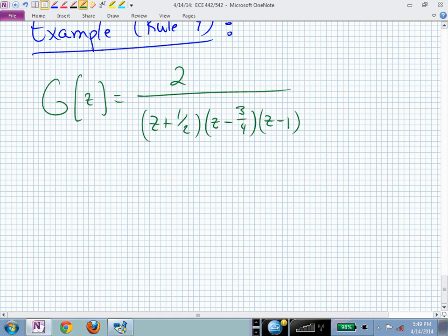How many finite zeros do you have? 0. You do not have any, and you have 3 poles. That says then that our pole zero excess, which I said, oh, today let's call it pz sub e, is 3.